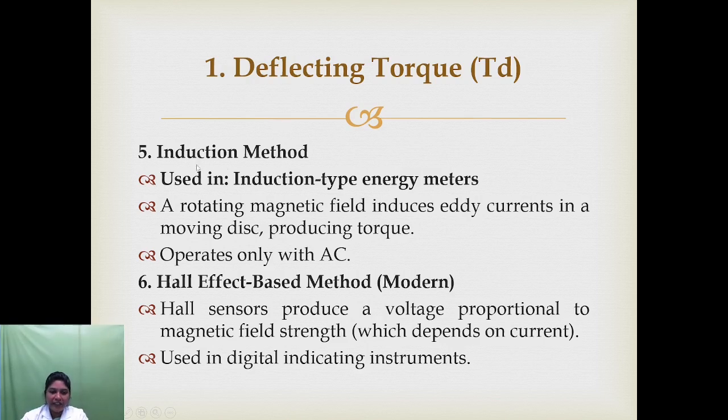Next is the induction method. It is commonly used in induction type energy meters. When a closed path is provided, there will be a flow of current in the disc, and due to the interaction between the induced current and the alternating magnetic field, a force is produced which causes the disc to move. A rotating magnetic field induces an eddy current, which moves the plate and produces the torque. So this is called the induction method.